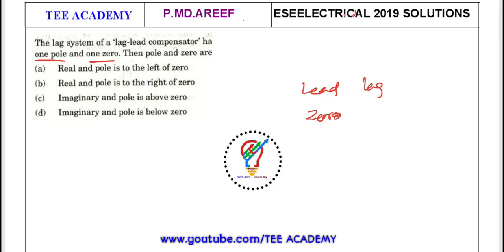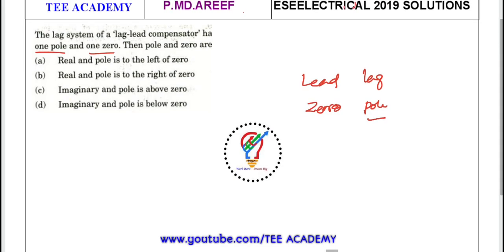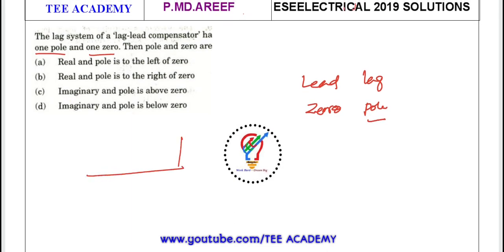For a lag compensator, the pole will be nearer to the origin. But the question is about a lag lead compensator, so we will draw this diagram. First lag: the pole will be here, the zero here. Now for lead, the zero will be here and the pole here.